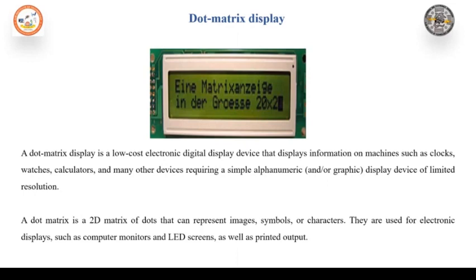The 5x7 format enables a far larger set of typically 192 characters to be obtained, including all the numerals, upper and lowercase letters, together with Greek letters and other symbols. A 7x9 dot matrix format provides a better representation of lowercase letters.